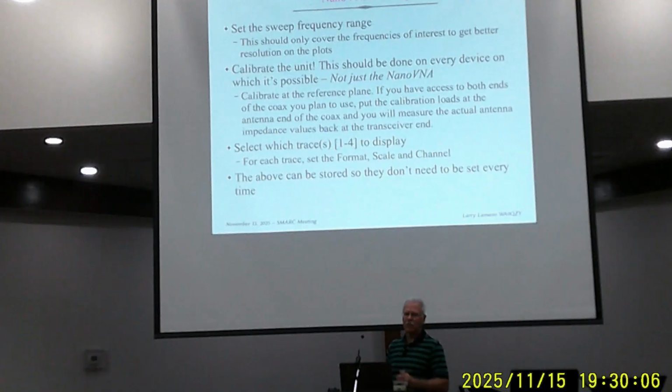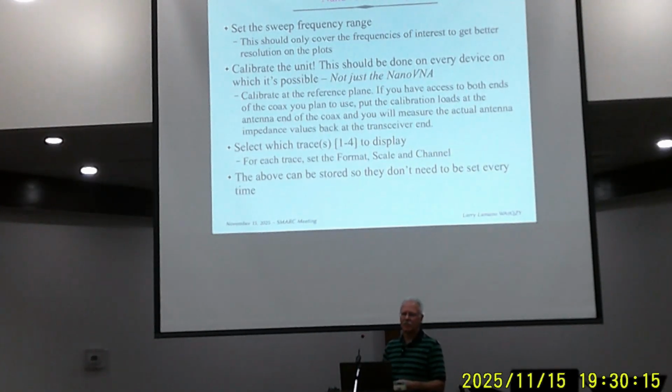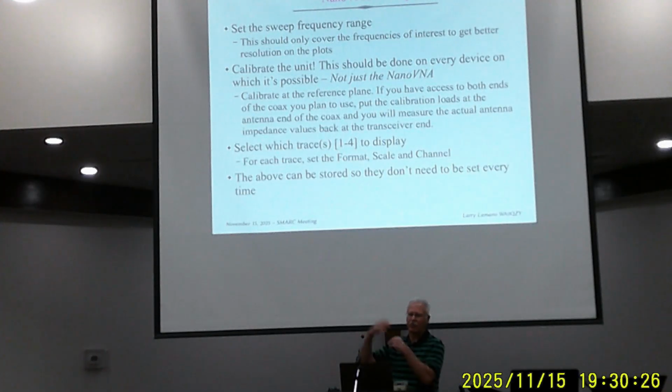But will it handle? I've got an inverter that... Well, measure the impedance and the SWR, and typically you just want to know what it is at the balun, because that's what you're feeding. The other side of the balun is next to the antenna. You might calculate the transmission line separately, but it'll give you a good idea.